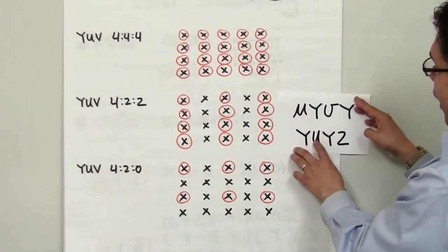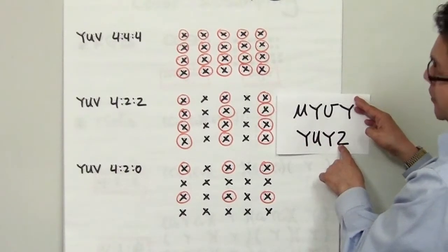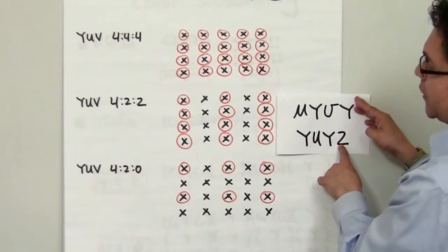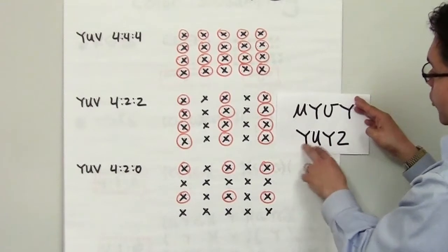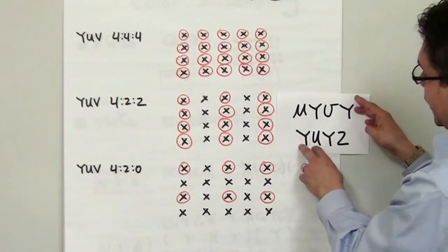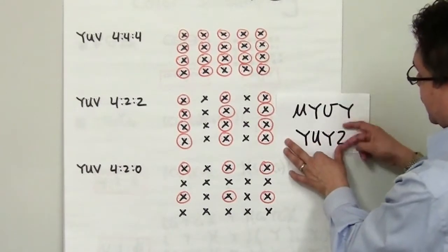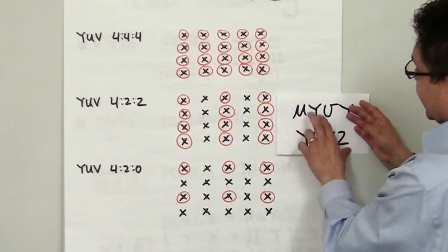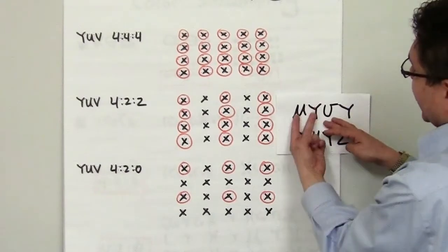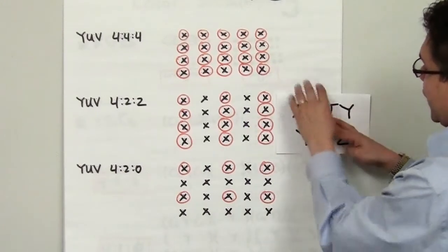For instance, YUY2, for 2 meaning a factor of 2 subsampling in the horizontal direction. It's only 4 characters, so therefore there are only 4 letters used here, but essentially this will be equivalent to this. There are other 4cc codes that represent the image, but they represent perhaps byte ordering changes in little endian or big endian machines.